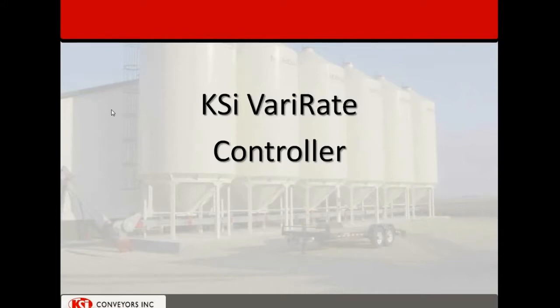The only requirement is that there is a scale with a hopper, as this VariRate controller uses loss and weight technology to deliver the seed flow at a specific rate. So it's going to be looking at the scale, at the loss and weight on that scale, monitoring that loss and weight 10 times per second, and making adjustments to the gate to deliver your target rate.